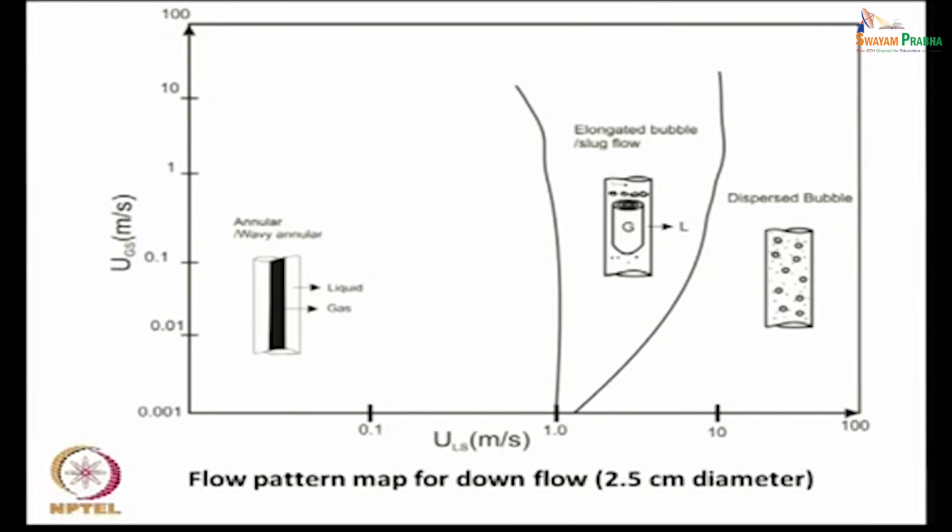There can be many more ways, but remember one thing: just learning flow patterns is not sufficient. You have to identify the flow patterns which operate under different conditions, and you also have to know the range of existence of the different patterns. The graphical way is definitely one. There are other ways also. One particular way is to actually model the transitions and develop mathematical equations to predict the transitions.